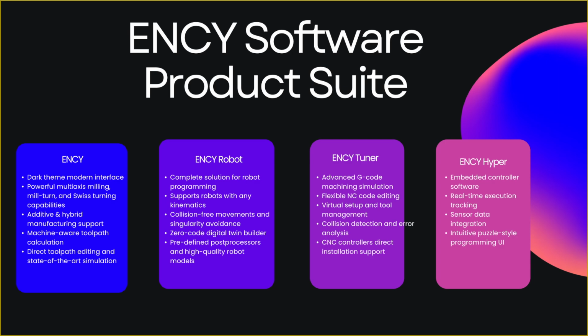And you have to pick some other things as well, besides giving it the G code. You have to pick the machine, you have to pick the post processor, you have to define the tools that are used, and after that you have a really good reverse engineered program that with some minor changes can be changed and saved again for further changes.